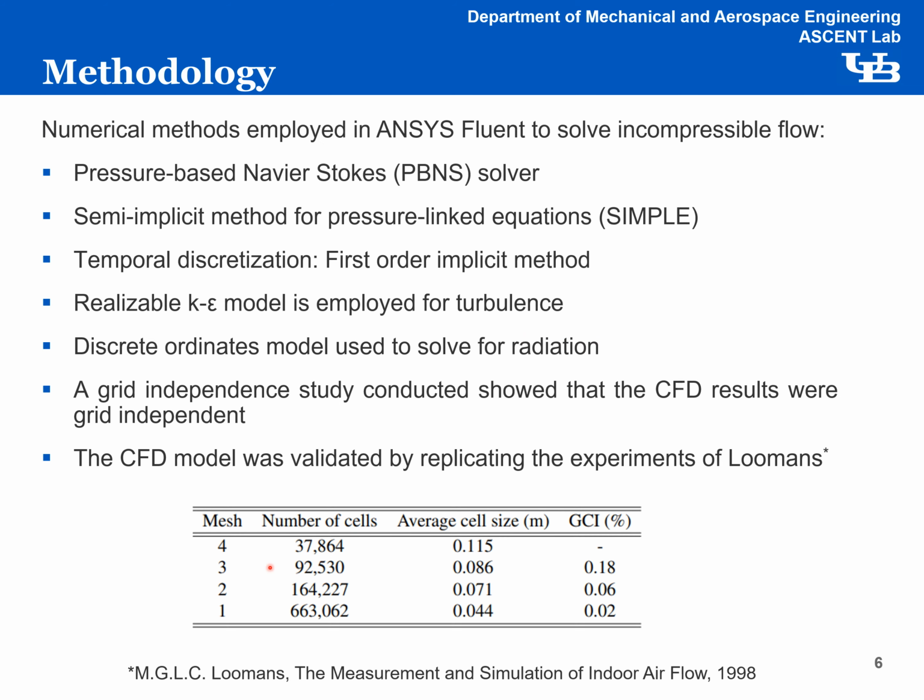The CFD simulations were conducted using the pressure-based Navier-Stokes solver in ANSYS Fluent, and the turbulence in the computational domain was predicted using the realizable k-epsilon model. Radiative heat transfer through the semi-transparent windows was solved using the discrete ordinates model, which acted as an additional source of heat for the exterior rooms.